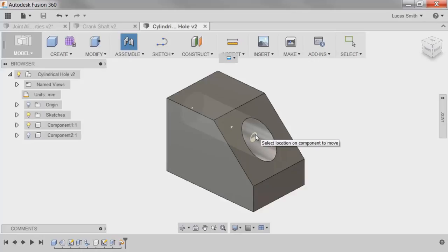To make it even easier to select these points, you can lock the cylindrical face as the input geometry by holding down the Control key, or Command for Mac users, and any of these points can be selected even when they're located behind exterior geometry. This eliminates the need to rotate the model in order to select these points, which greatly speeds up creating joints using cylindrical faces.